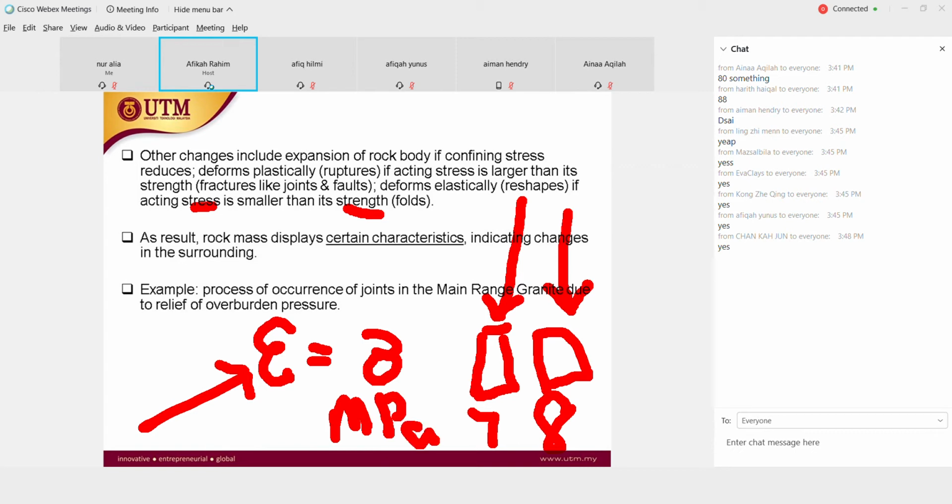Okay, so don't ask me, if it is the same material, for example, if you compare slate A and slate B, will they produce the same value of compressive strength? The answer will be no. Okay, but it does have a range. For example, 1 to 20, say, for gypsum. Okay, so that's it, 1 to 20. If you go beyond, maybe we can tolerate 5 MPa. If you go beyond, meaning that it is not pure gypsum, for example.